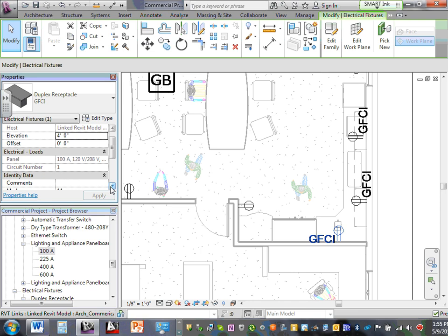The power button won't come back. I don't even get a select panel. If you click electrical, here you go, skip whatever function you're in. Click on this one. There you go. So you select panel, grab here, here's preview panel. Now you're circuited. And how do you know? You see that here? It says circuit number 1. You're good. You're circuited for that one.